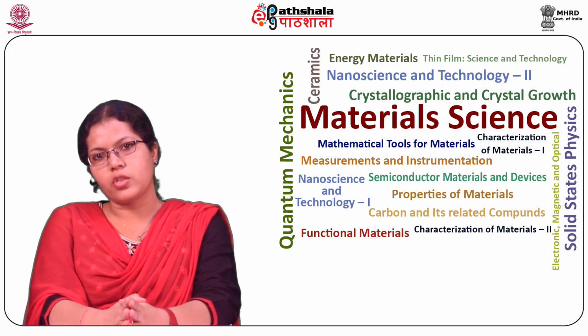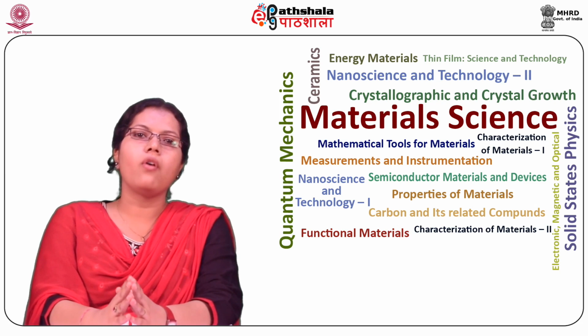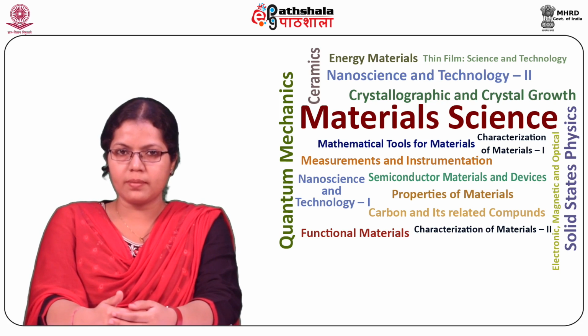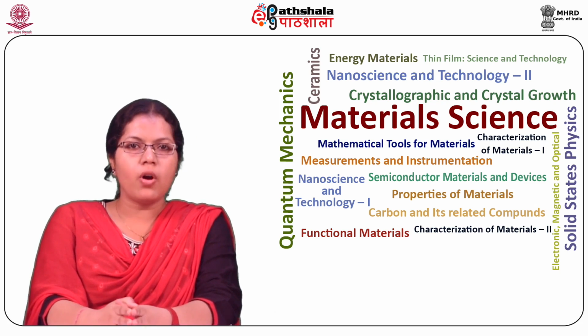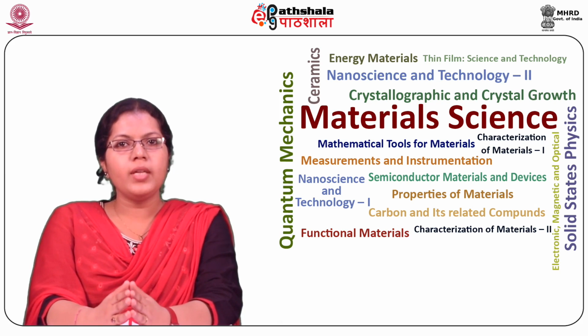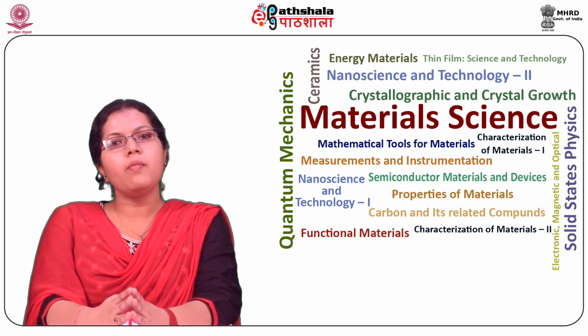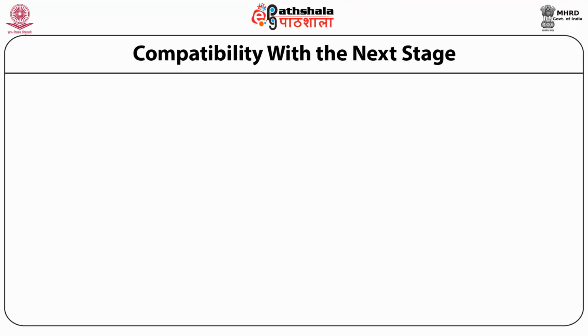Physical conditions of the transducers and also the measurement are very important for the selection of transducers. These must also be taken care of. First, the room or available space to mount the transducers is important. Second, whether the measurement is static or dynamic will also decide the type of transducers to be used. Third, how much energy can be extracted from the measurement to do the measurement without loading is an important parameter for deciding the transducers.